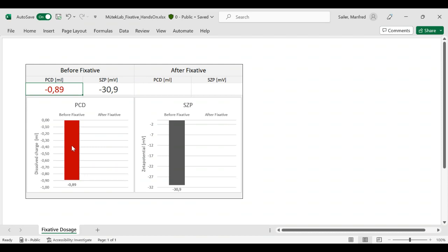And if you're trying to add additives onto the fibers, like starch or any strength resins, grease barrier chemicals, you must take into account that a portion of this fiber additive will be consumed by this anionic dissolved charge here, and that only the rest of your fiber additive will make it onto the fibers.